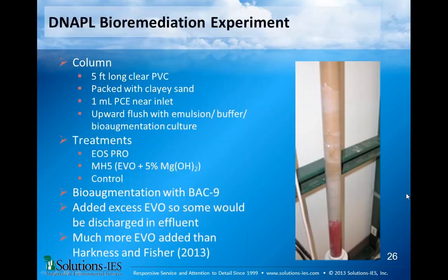Okay, and the next question on that, the follow-up, is what are effective approaches to help control biofouling that can occur with bioremediation systems? I think operating experience is that if you do emulsified oil, biofouling is much, much less of an issue because basically it takes weeks or months for the bacteria to grow up around the injection well.